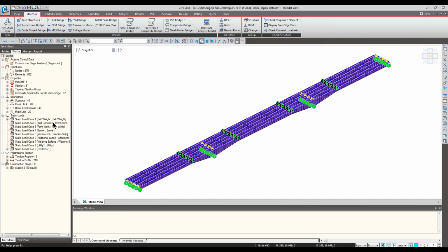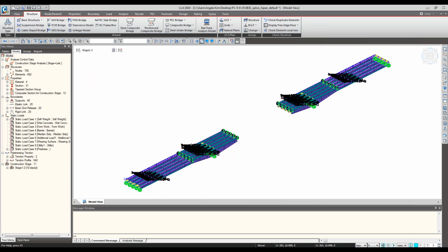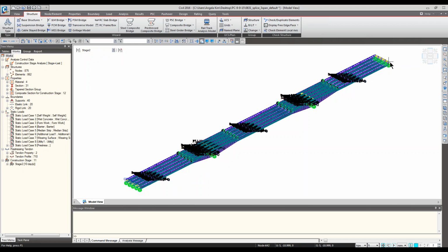And over here, if you noticed, let me display my tendons. The tendons have been there for the girders. So these are the pre-tensioned tendons. And then you can post-tension them once they are all placed. So you can make them continuous. You can apply the first post-tension.